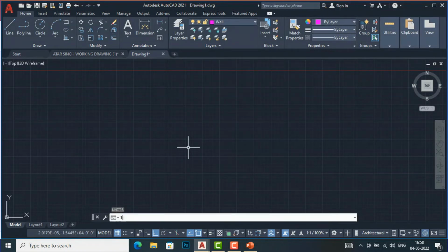Okay. Now after this you are required to set limits for your drawing area. I will make a detailed tutorial on how to draw your floor plans in AutoCAD. Now if you set limits, it asks to specify the lower left corner, 0 feet 0 inches, 0 feet 0 inches. I will leave it as default and press enter. Now it is asking to specify the upper right corner, 35 feet, 24 feet. I am going to increase this value to 400 feet comma 500 feet. You can use any other higher value also, and I will make a detailed tutorial on what the advantage is.